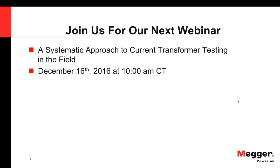Unbalance between the phases typically occurs because of unbalanced loads. You have higher loads on one phase than on the other, which will create the unbalance. You can also have unbalance occur due to solar tiles if they're hooked up to only one phase.